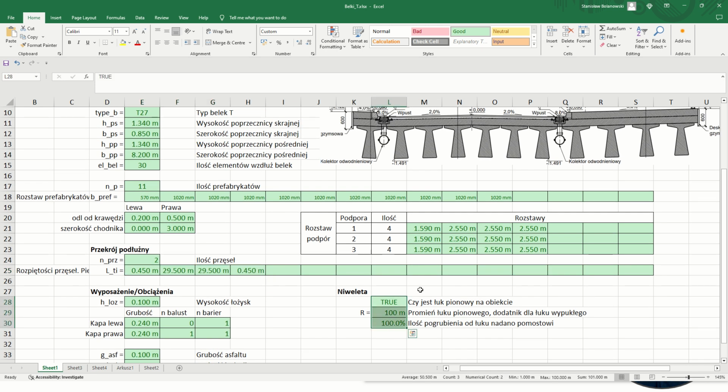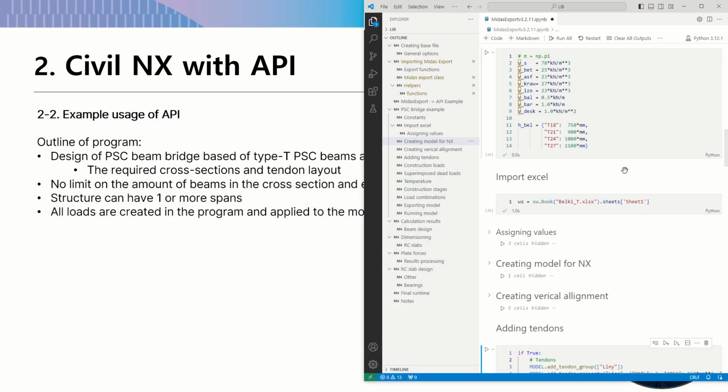I added here a point for the vertical curve within the bridge. This then allows, if we have a beam that is horizontal and it starts at 2 points, it'll be a straight line between those points, but then the roadway can be in a vertical curve, which would cause more concrete in the center of the beam than on the ends of the beam. So here's just an exaggerated example of 100 meters, and to show what that would look like in the model. And then everything here is then exported to MIDAS Civil.